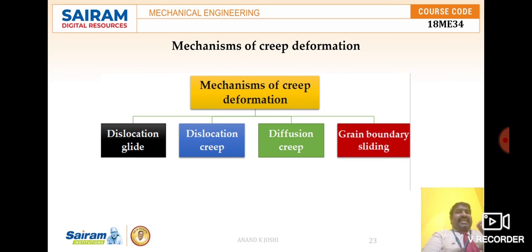So the grain becomes longer, since the applied stress does work, and the process is faster at high temperatures due to the existence of more vacancies. Over a period of time, the movement of atoms elongates the specimen in the direction of the stress, and it contracts in the transverse direction, resulting in creep. So this is a brief account of the mechanisms of creep deformation.